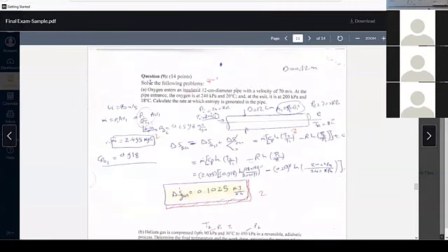This is how to get the entropy, which we did in review 3. We have delta S system and delta S surrounding. Because it's adiabatic, isolated, there is no heat going out or in the system, so there is no surrounding, only the system, which should be positive. And this is gas, just M. You remember CV ln T minus R ln P, or CV ln T plus R ln V ratio. So you can get delta S. You just need to make sure you have all the temperatures and pressures. And you have the mass flow rate, and the heat capacity, which can be obtained from table A2A, unless otherwise mentioned. You have all the information, P1, T1, V1, and so on. So you can get delta S generation, which is the same as delta S system because it's insulated.